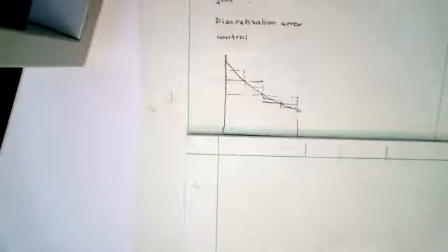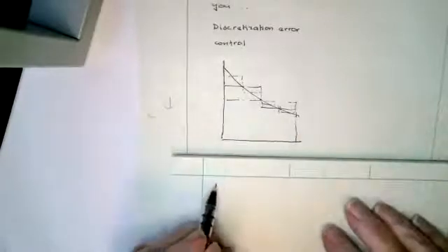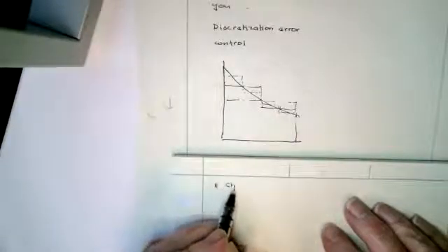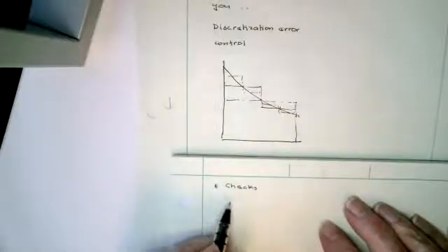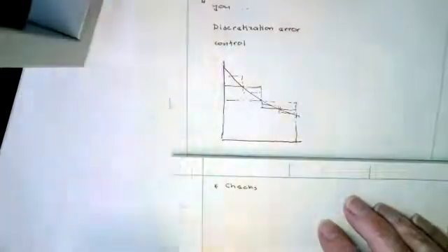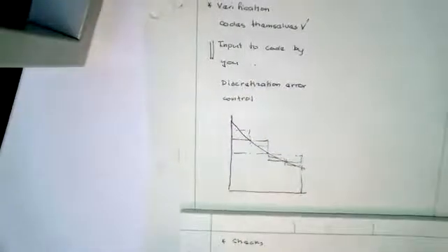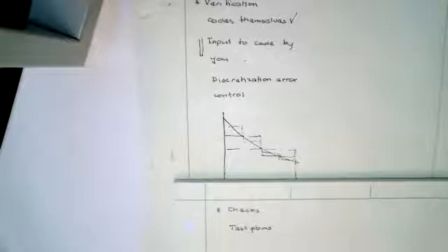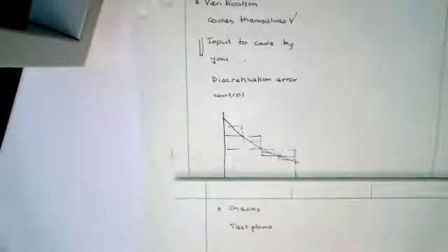Let me just finish with a couple of things about checks. So how do you beat these problems? Well, you want to do test problems. You don't want to just start off doing the problem that you wanted to do. You've got this configuration, and you went and looked at Peterson, and you said, well, I can make a rough estimate from Peterson, but it's not very good. I'm going to analyze it. Then you want to analyze something. So you want to take something from Peterson that's similar and see if you can do it.